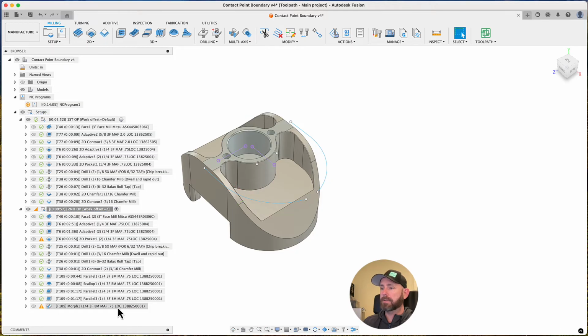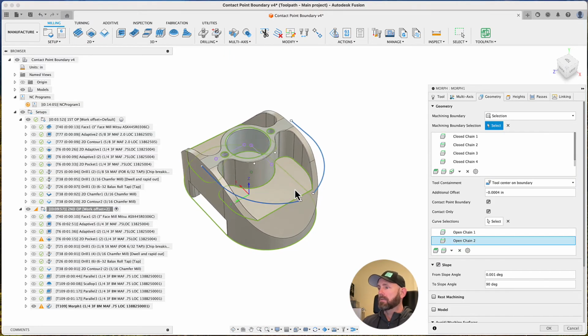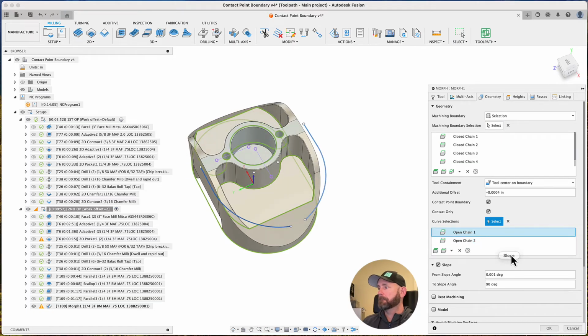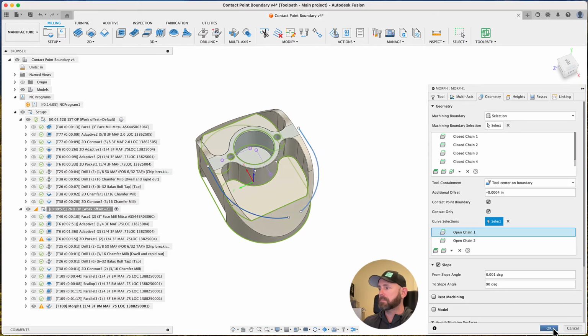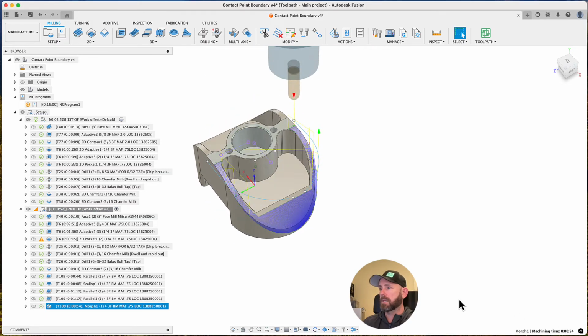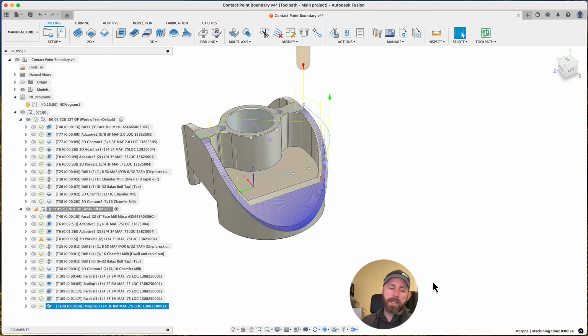We have an empty toolpath. So I have to figure that out. So let's come here. What happens if I turn that this way? Yeah. So with a morph toolpath, my buddy Rob Lockwood said this one time, and it really connected with me. Those arrows have to be pointing, these guide curves need to be pointing the same direction. You'll get a nonsensical toolpath or an error, but it's like taking a napkin and twisting it. That's basically what's happening with the toolpath when they're going opposite directions.